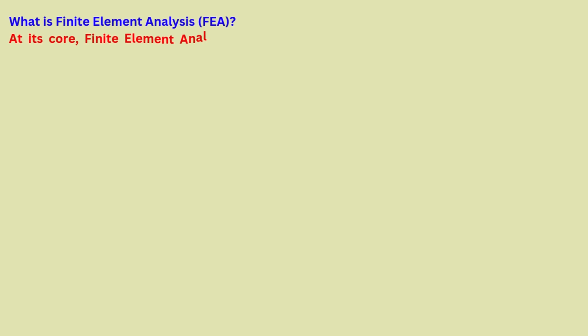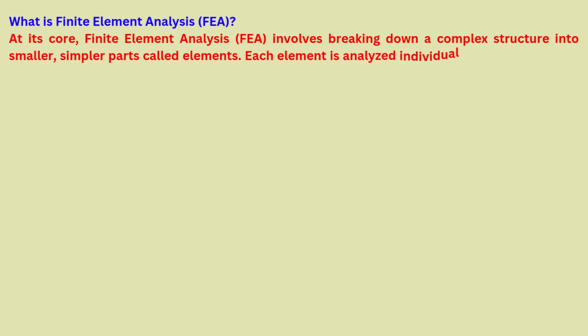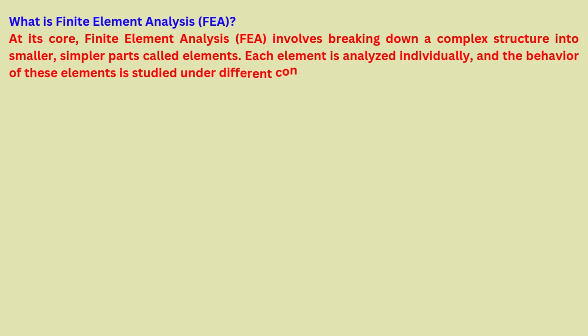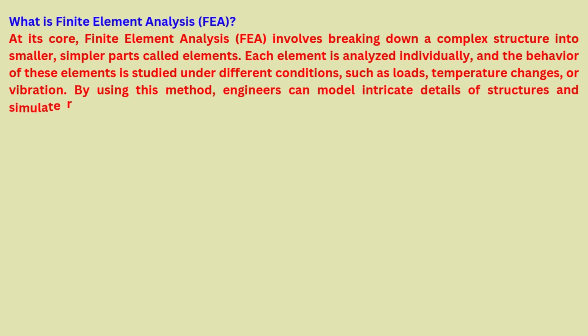What is finite element analysis, FEA? At its core, finite element analysis, FEA, involves breaking down a complex structure into smaller, simpler parts called elements. Each element is analyzed individually, and the behavior of these elements is studied under different conditions, such as loads, temperature changes, or vibration. By using this method, engineers can model intricate details of structures and simulate real-world behavior.